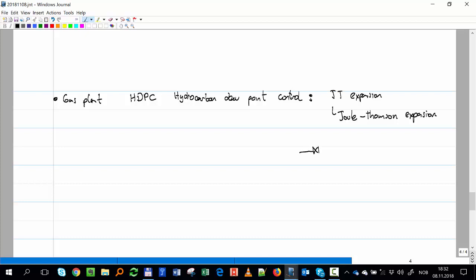If you remember, with the temperature, a drop, right? In our case, it was not so big, I think it was a few, like 30 Celsius or something. But if you have a very large pressure drop, you will have a very high drop in temperature. And with this drop, then you get a lot of the liquids, the condensates, water, etc. So this is just valve expansion.